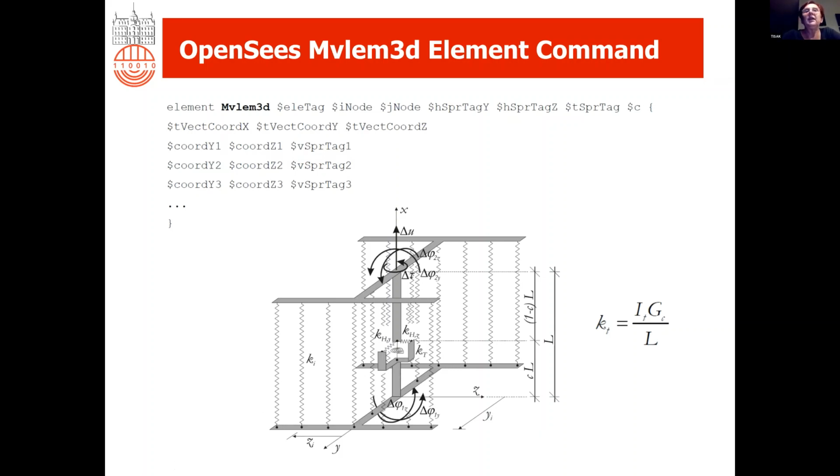So this was a 2D element. The 3D element is similar, but in the local coordinate system, for example, instead of 3, we have 6 degrees of freedom. Again, the rotation in both nodes, elongation, and the one which is added is also the torsional rotation. And the command to input the data is similar as for the 2D element, but we have to define 2 materials